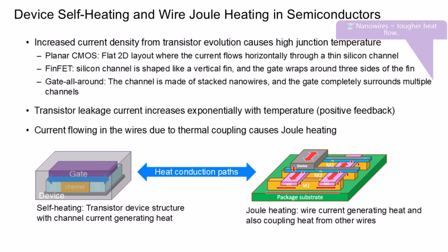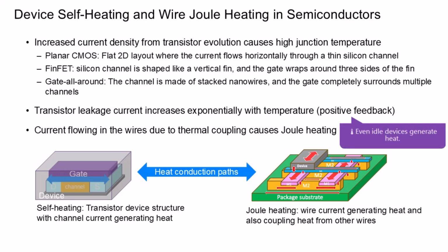The next generation gate-all-around devices pack even more nanowires, complicating the heat conduction even further. When the devices are not active, the leakage power can also introduce heat inside these devices. And the thermal coupling in these 3D transistors is definitely critical to understand.